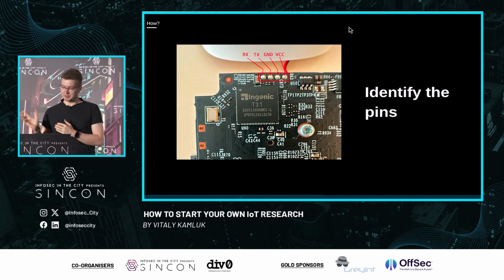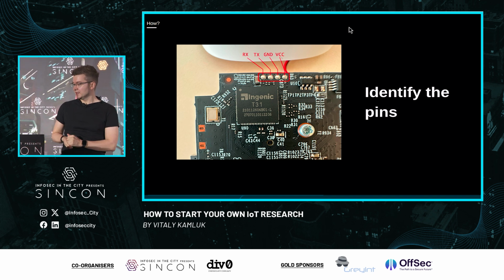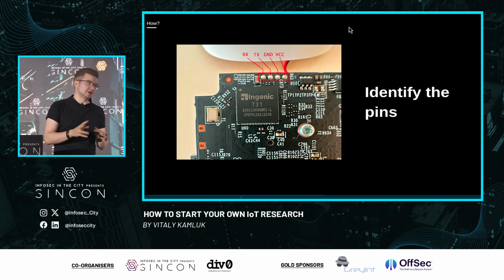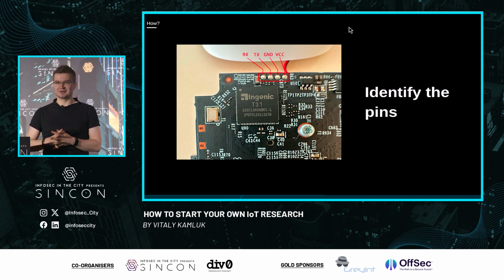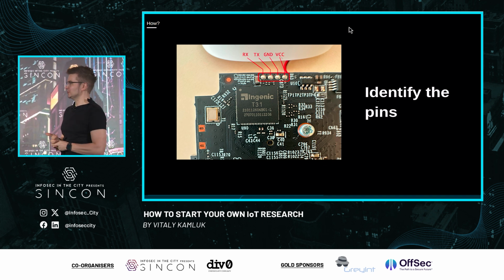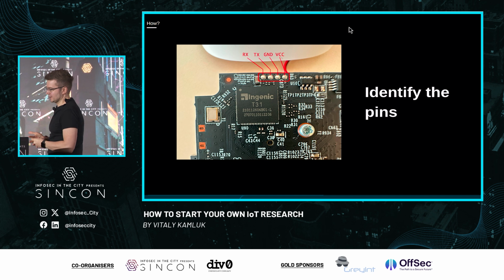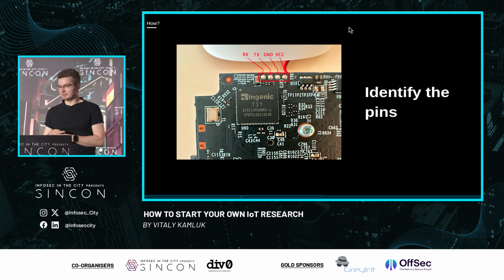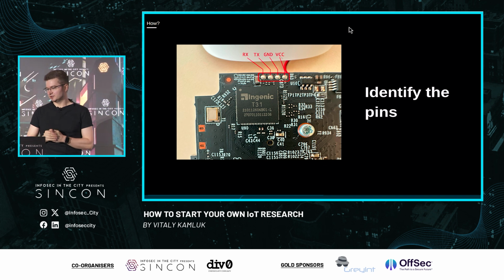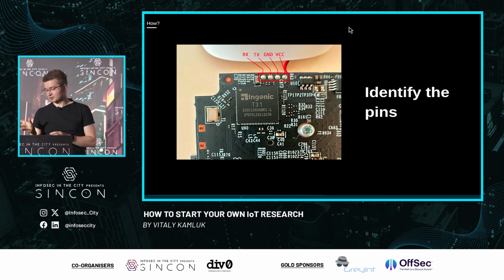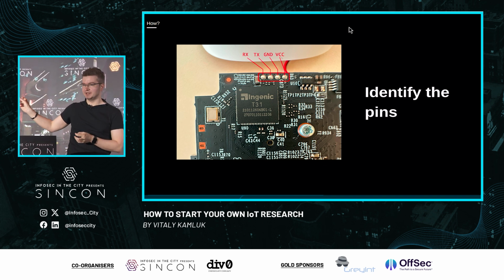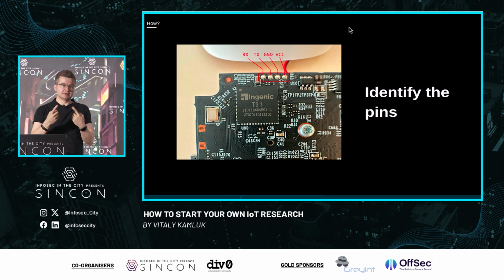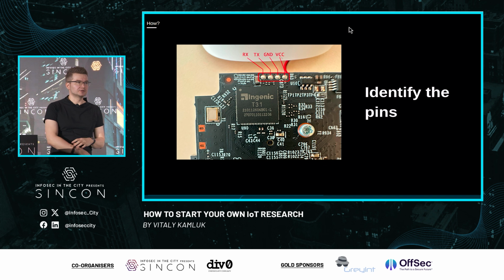So, okay, once we figured out where the VCC is, now there's just 2 left, RX and TX. You can pretty much try and guess it with just 2 combinations, right? But to do it in a more organized fashion, you can again use the voltmeter to check the voltage fluctuations. There are 2 pins, RX and TX, for receiving and sending data. So it's kind of two channels, receive and send data to the device.